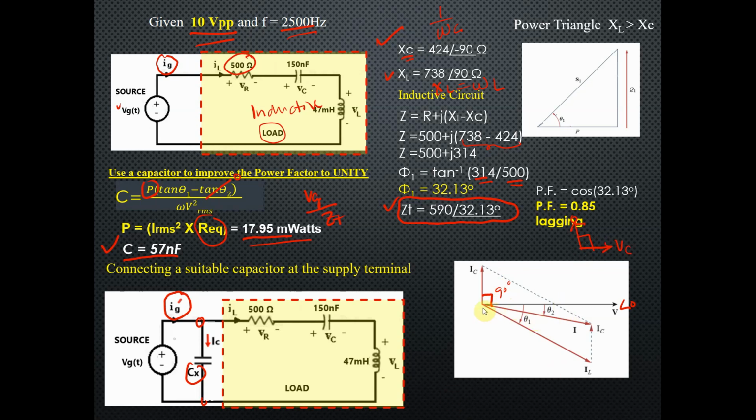with respect to the source reference. And what will happen? This phasor will reduce this phasor. It goes up. You add it using phasor analysis, and then after that, you connect this one here. It will be reduced, right? This will be subtracted from this one. You can observe that the length of IL is longer than I, and I here is IG prime. So we can say that we have reduced the value of the current. Okay, so there is a power factor correction there.